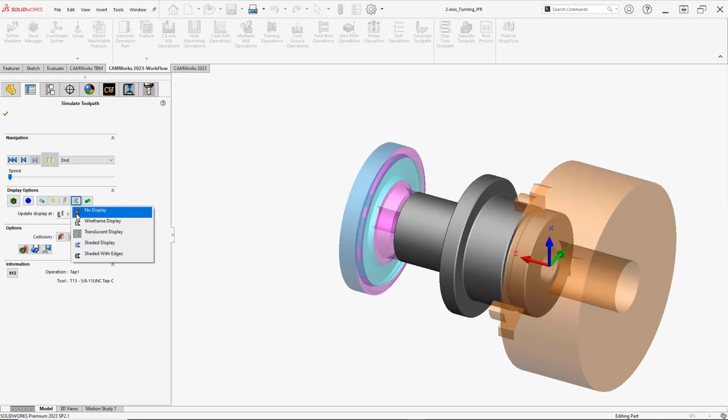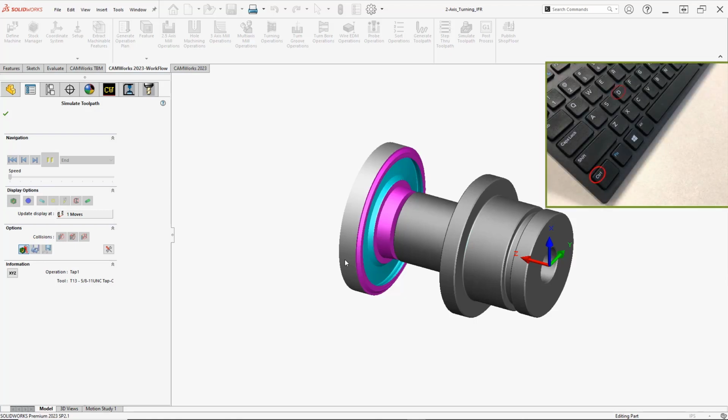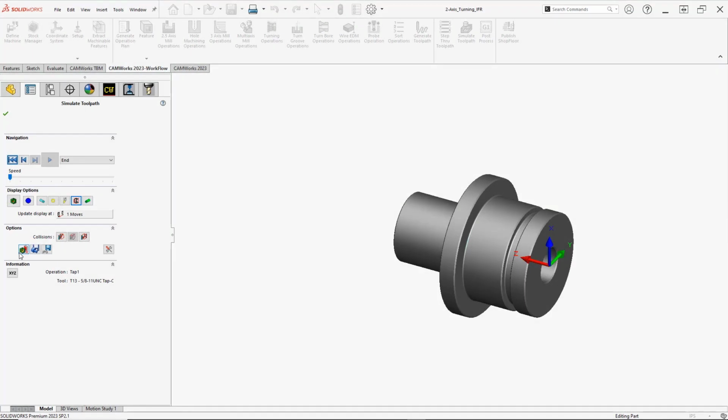In some cases, the cutting tool created loose stock chips or remnant material in the display area. To address this, the Select Chips and press the Ctrl D key button is used. Simply click this button first, then graphically pick the loose stock chip to remove. As each chip is selected, its color changes. When all the chips are selected, press the Ctrl D key on the keyboard to remove the chips from the display area. To turn off this function, click on Select Chips and press the Ctrl D key button once again, as the next step is to show difference between the machined part and the design part.